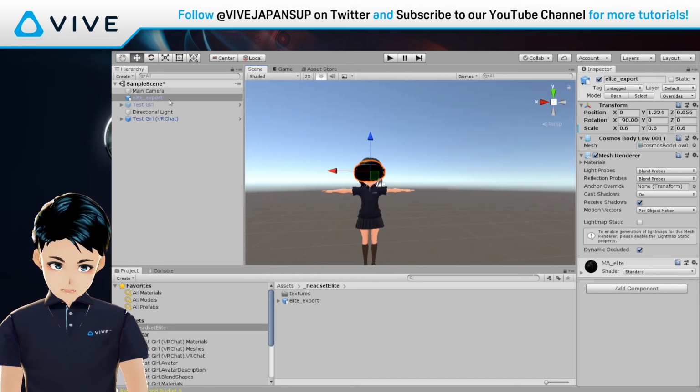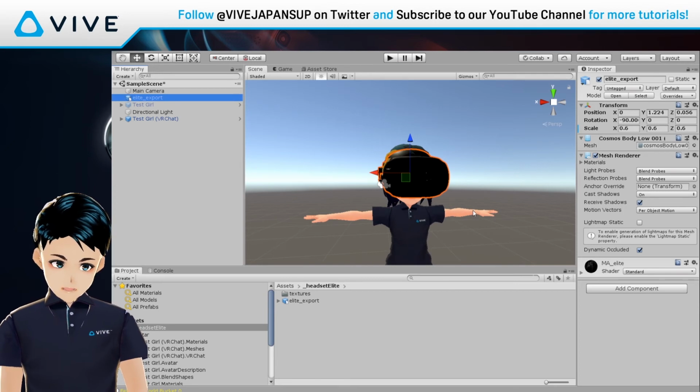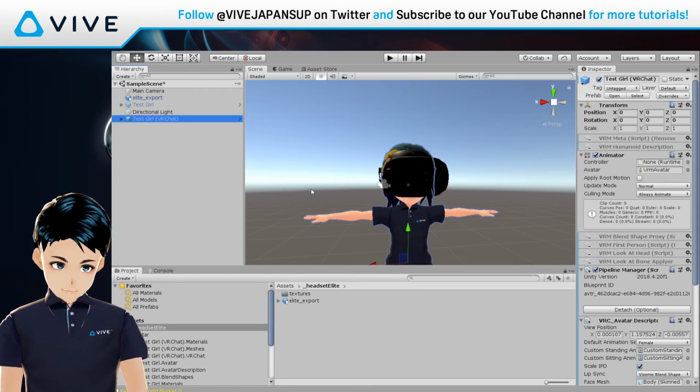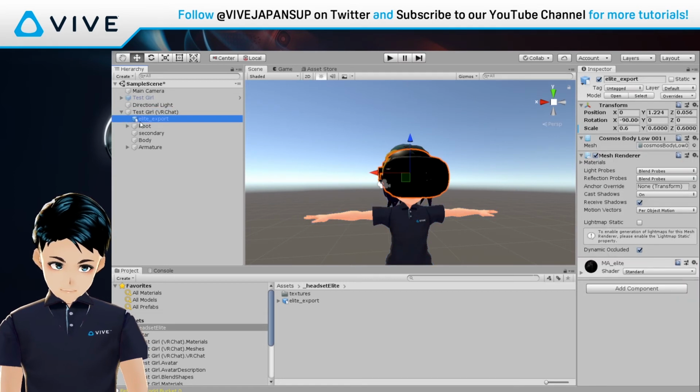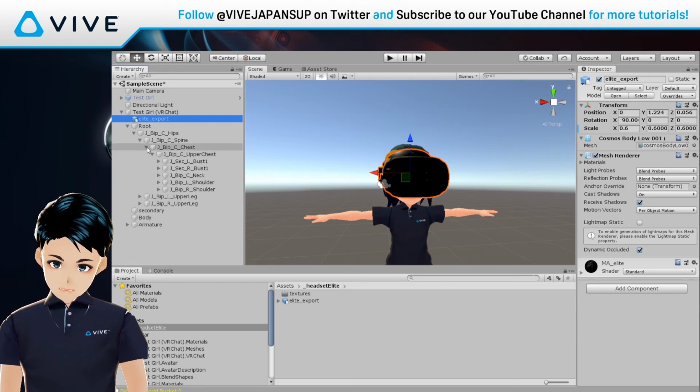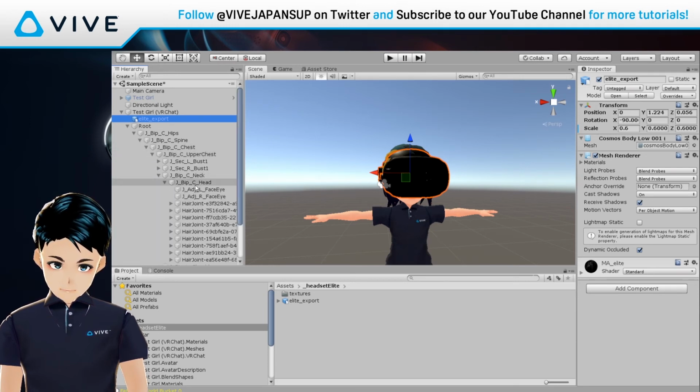So if you were to import this and save to VRChat by itself, they're not even in the same object. They're not going to be attached to each other. So first of all, you're going to have to unpack this prefab and then toss it in here. But the issue is that it's going to just stay floating in the air when your whole body is moving around. You need this object to be attached to something that's going to move around, and in this case it's her head. So you want this object to be moving with the whole head.